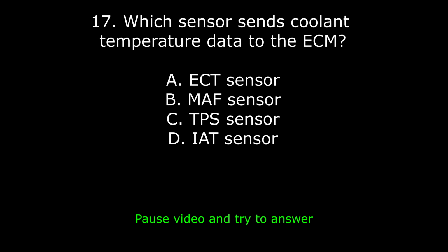23. Why should refrigerant lines not be bent sharply? A. Restricts oil flow. B. Increases system pressure. C. Damages compressor. D. All of the above. Answer: D. All of the above. Explanation: sharp bends restrict flow, increase pressure drop, and reduce lubrication.